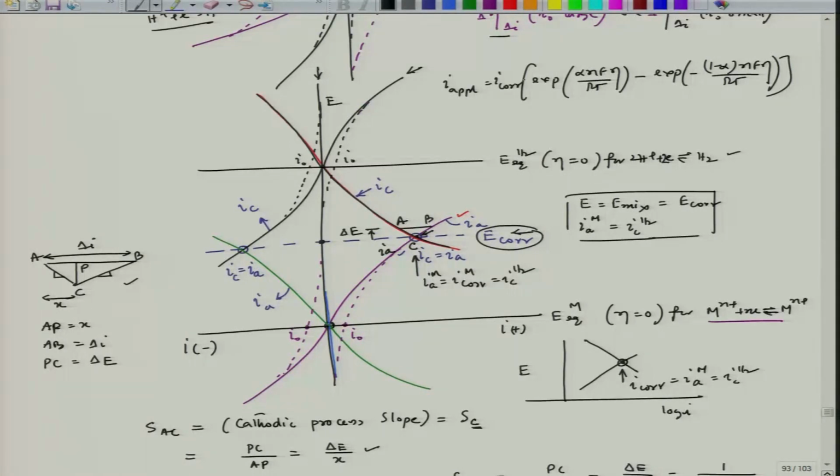we could see that that equation is validated, because here it was I0 in this particular case, and in this hydrogen case this was the I0, but at this steady state E_corr potential, I could see that these two current densities are also equal. So, I could have an equivalent equation for these two cases, anodic and cathodic cases at steady state E_corr.